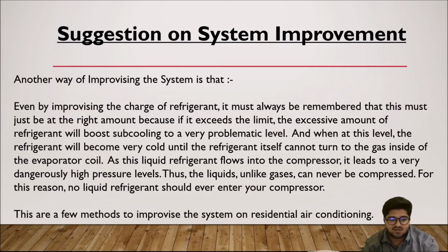As this liquid refrigerant flows into the compressor, it leads to dangerously high pressure levels, because liquids, unlike gases, can never be compressed. For this reason, no liquid refrigerant should ever enter your compressor. So, these are a few methods to improve the residential air conditioning system.